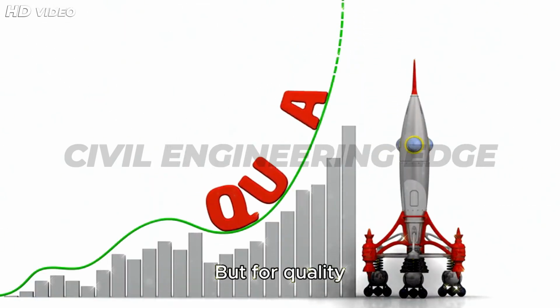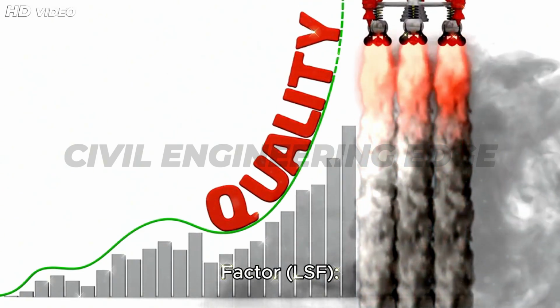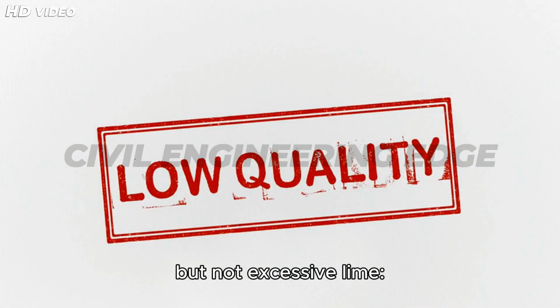The Bogue calculation estimates the proportion of major compounds like C3S, C2S, C3A, and C4AF. But for quality control, we directly measure: 1. Lime saturation factor, LSF. Ensure sufficient but not excessive lime.